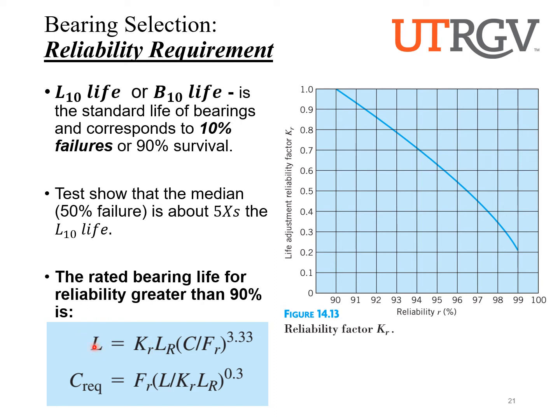So what does that mean? Let's make some super dumb numbers. Let's say a bearing was good for 100 revolutions. It's not unrealistic, but let's just say 100, just for the math. So at 100, it's good for 100 revolutions, and you'll see 10 out of 100 bearings fail. But if you only want to see one, then you would only have to limit that life to just 20 revolutions, or 20% of that. Again, that's for the life. So what we're doing is taking just a fraction of the revolutions and saying, we're going to put our seal of approval that it's only good for less life.